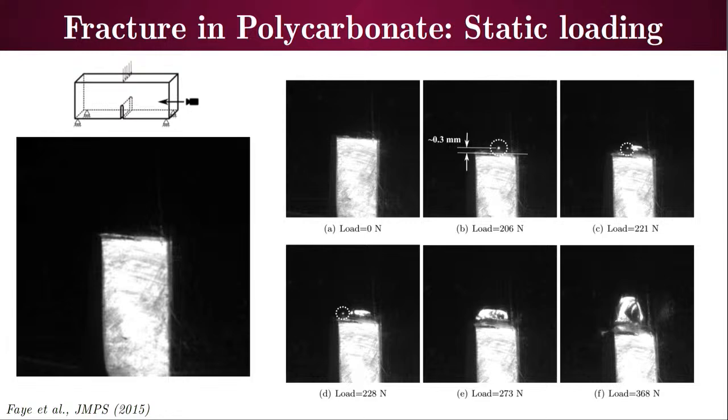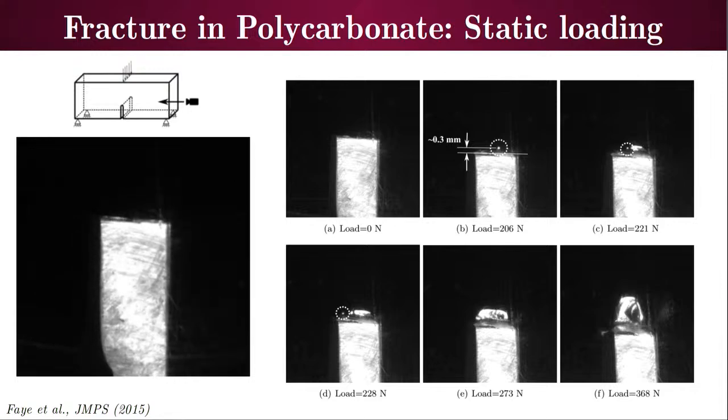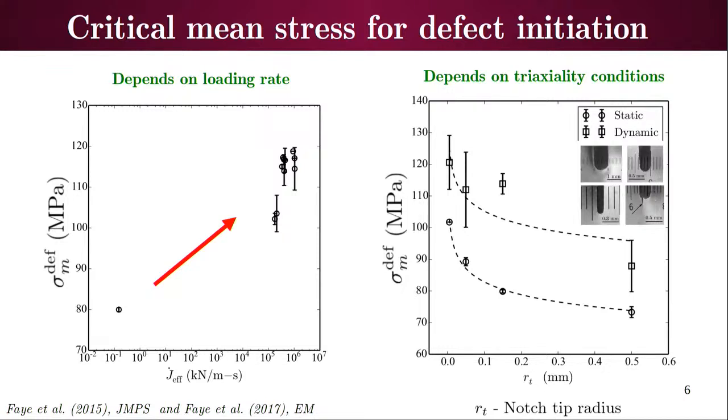No, but you compared this case with that impact loading. No, this is just to motivate why the void growth is important. What we want to understand here is that voids are causing the failure; voids are a precursor to failure. We actually compared these results, and the mean stresses required for defect growth or void growth increase with loading rate. These are all impact loading, and this is slow loading. So you can see this is the rate.